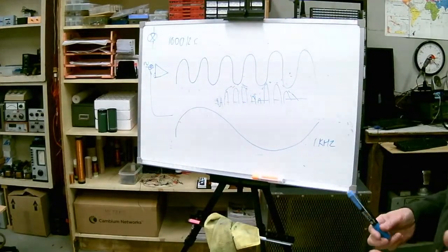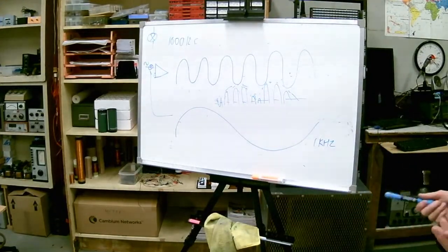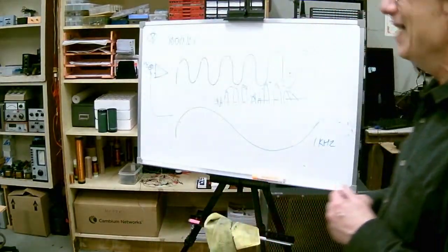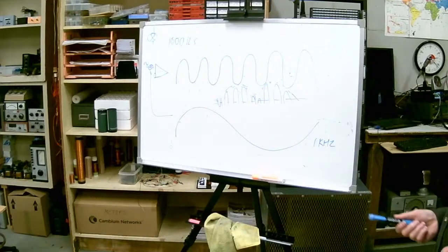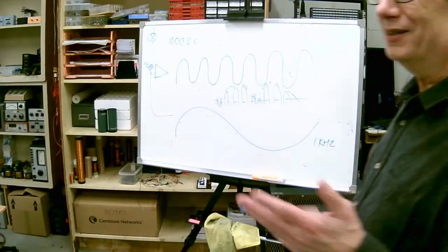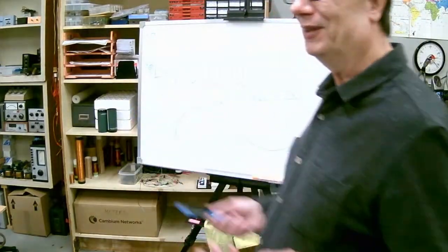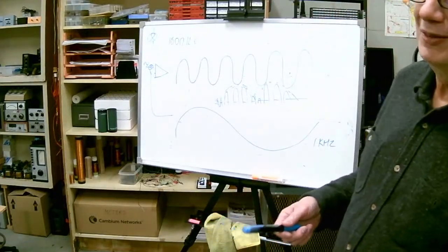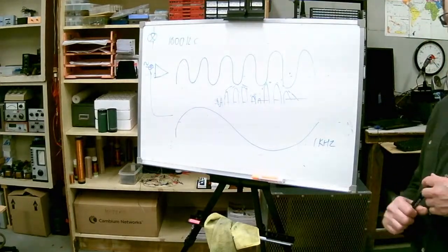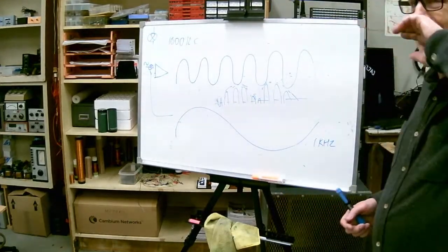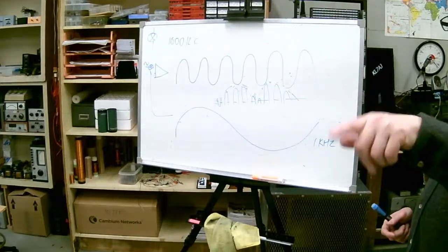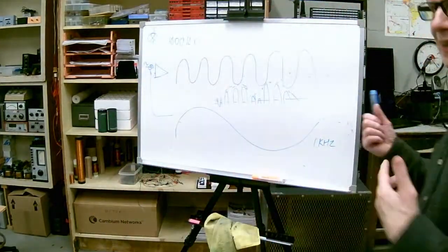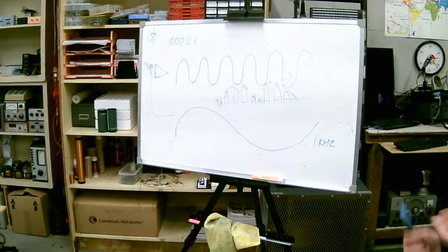Now, like I said, that's a very crude, inelegant way of doing it, but that's the way it was done for many years till we figured out how to amplify things. Think about a diode detector, crystal radio, you don't need any amplification. You rely on the power of the incoming signal to do everything for you. Because nobody had any amplifiers then. Everything was passive. Vacuum tubes didn't exist in the early days of radio. It was using spark gap. I showed you how I could resonate that circuit with just a battery and a shock. So that's how they generated radio, and the detector is pretty much equivalent on the receiving end.